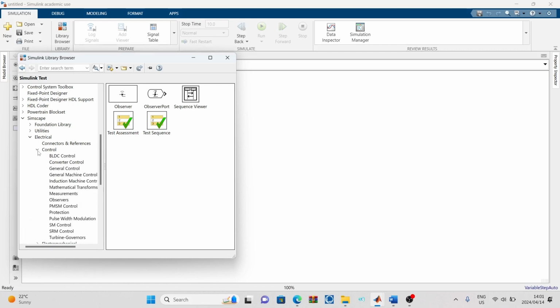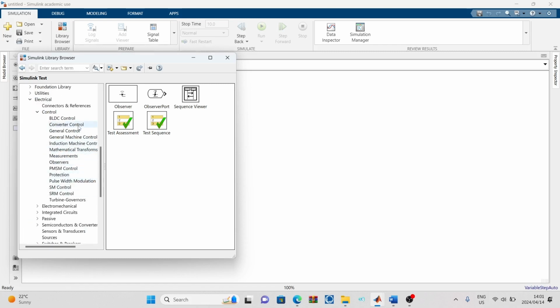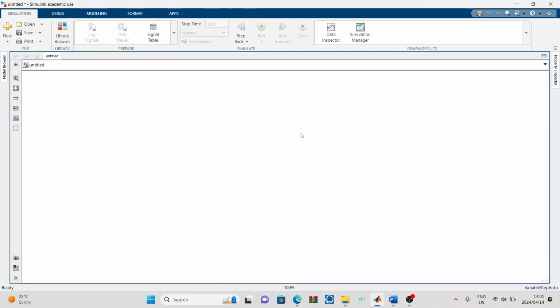You can bring in the components using your library. Let's see, if I select observer, then I just click on it and drag and drop. Just let's wait. So as you can see, it drops it here. Then if I click on it, I can move it in Simulink. That's one way to get your component.